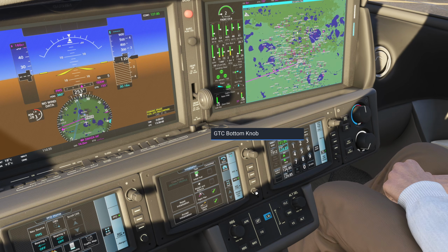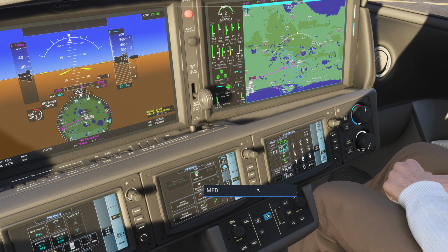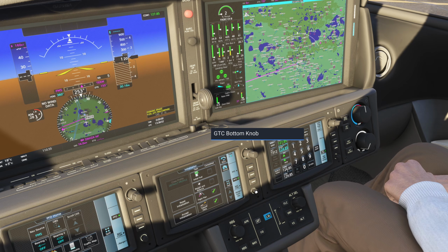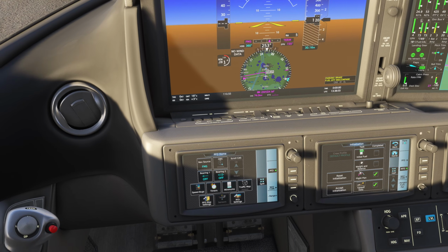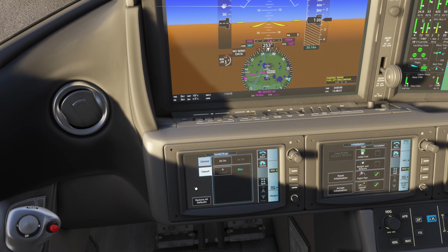For our takeoff, as we're started on the runway, we want to make sure we've got some things noted in our heads. We want to know our takeoff and climb speeds. So we go to the speed bug page, and we have the rotate speed set to 85 knots. So we're going to pull back on the stick at 85, and our climb's around 165 knots. I normally change it to 160, a nice round number.